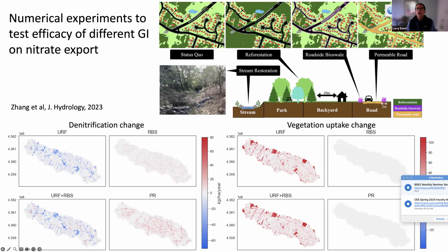There's extensive areas of lawns pulled out. Roadside bioswales, these areas on the side of the roads. So we're essentially putting in stub outs and putting in taller vegetation in these areas that'll absorb road runoff. And then in the low intensity streets, putting in permeable pavements.